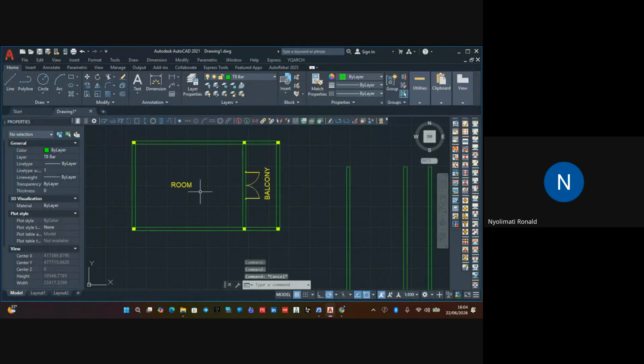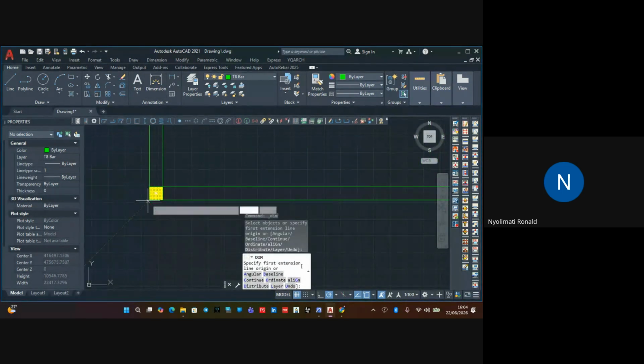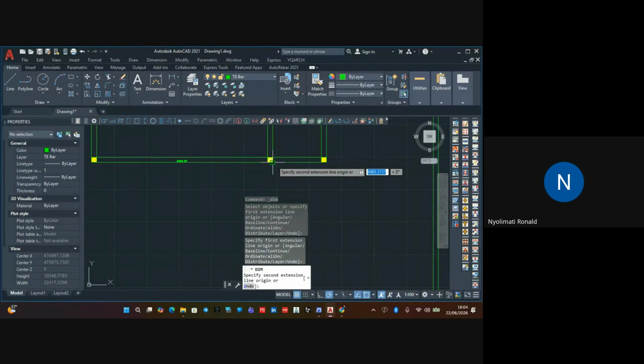Okay, so now this room you're seeing already, it can be reinforced. The floor can be reinforced with the Maxpan. Okay, you can design this room with a Maxpan. But this balcony, where sometimes people can gather in front, people can pass in from here, it needs a solid slab. Yes, because of the weight of the people around there.